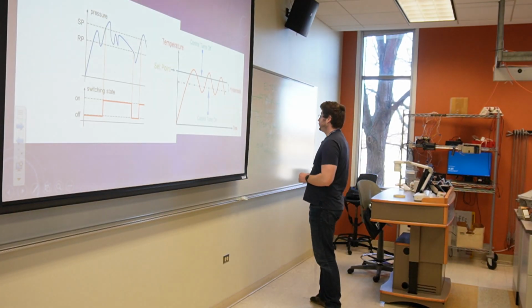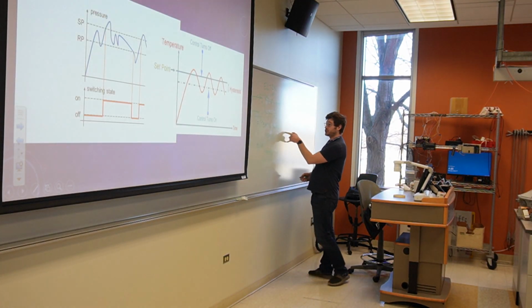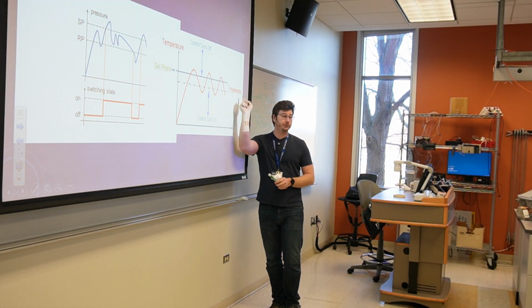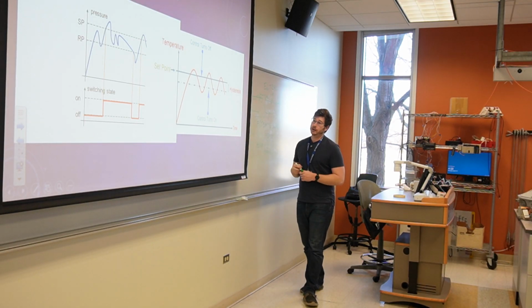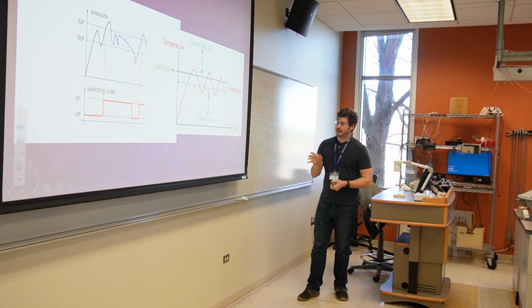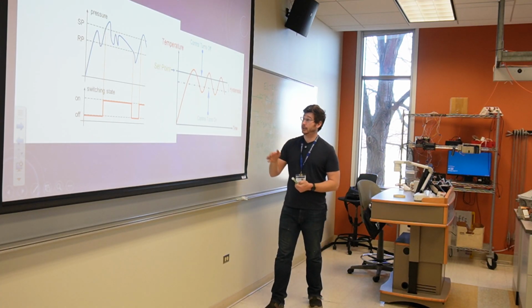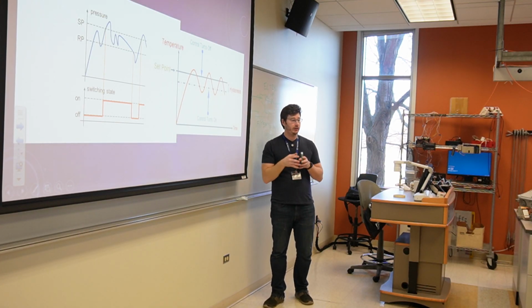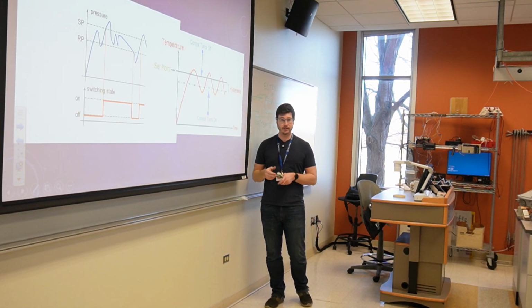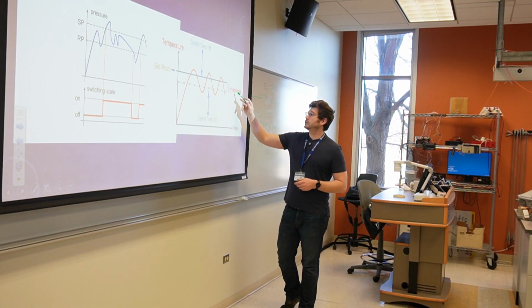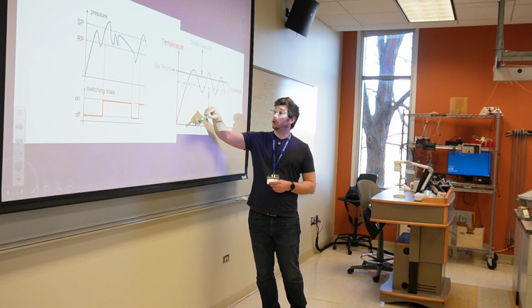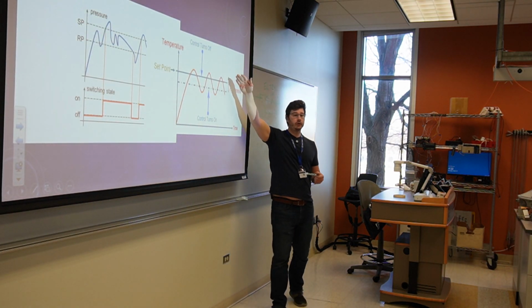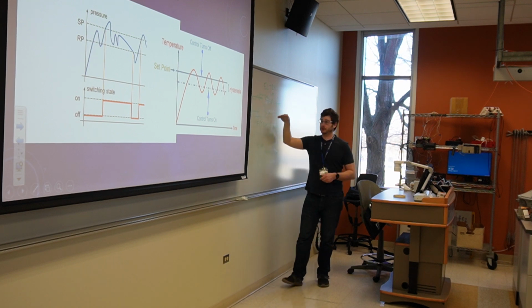The way that we can do better is just by changing our bang bang just a little bit. And the way that we do that is with this term called hysteresis. Hysteresis is a very interesting term. It's kind of difficult to understand, and it has multiple definitions. By the way, hysteresis is also a material properties thing. It's how metal, for example, can expand and contract volumetrically as it's heated up and cooled down. But hysteresis is a technique that we can employ to shift the set point just a little bit out of the way of our noise, which means that it won't constantly be triggering all the time.